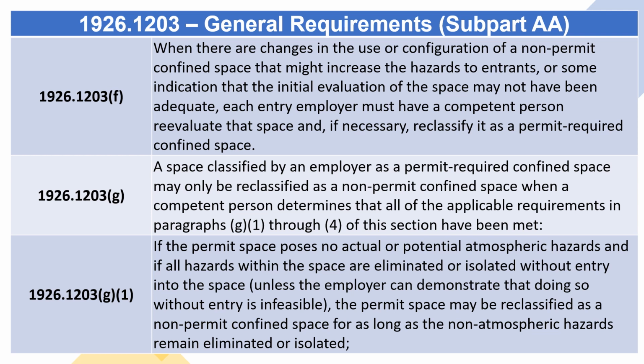1926.1203(f). When there are changes in the use or configuration of a non-permit confined space that might increase the hazards to entrants, or some indication that the initial evaluation of the space may not have been adequate, each entry employer must have a competent person re-evaluate that space and, if necessary, reclassify it as a permit-required confined space.